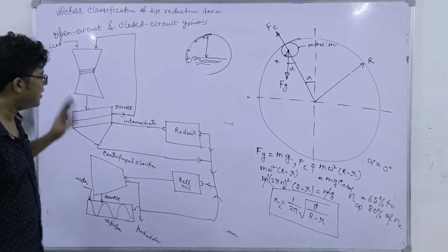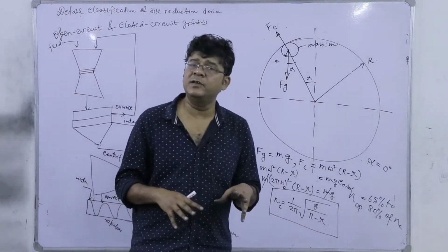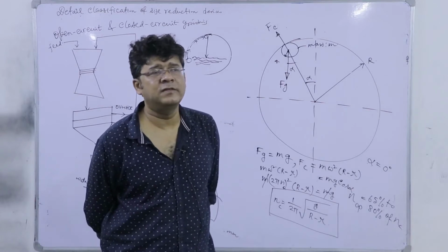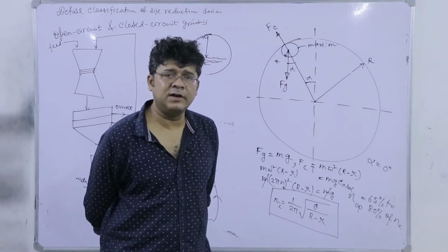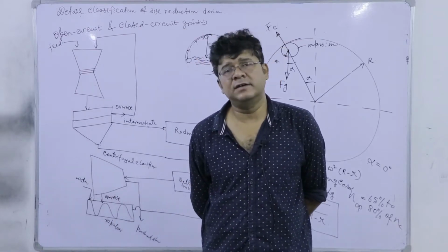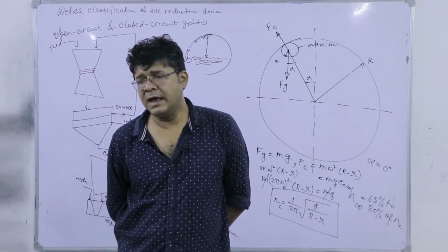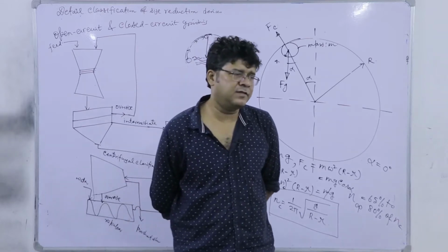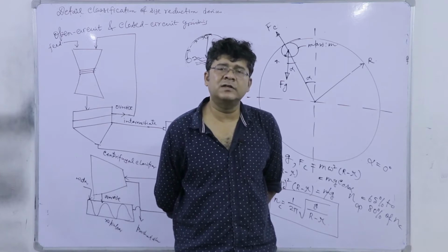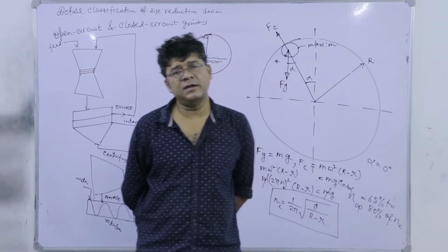Okay. So that's all about the size reduction devices. What we have to note here: the classification, the type of forces we use, the different power laws, that is the Rittinger, Kick, and more importantly the Bond law. In Bond law we have to note the definition of work index and the unit specific form of Bond's law, which is of real utility. And then we have the detailed classification of the size reduction devices into crusher, different types of fine and intermediate grinder, ultra fine grinder, and cutting device.